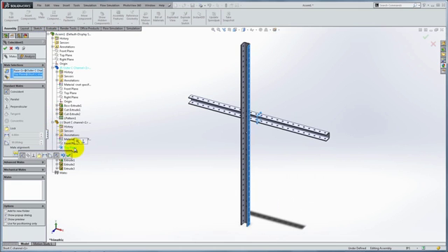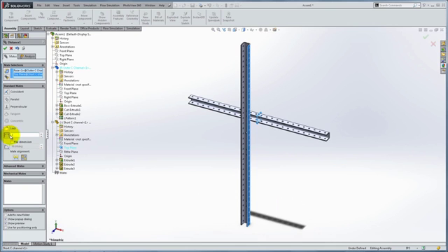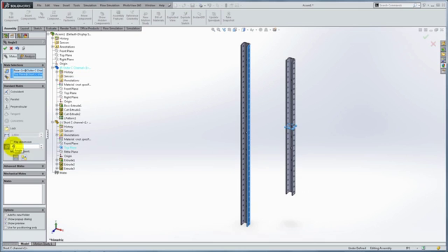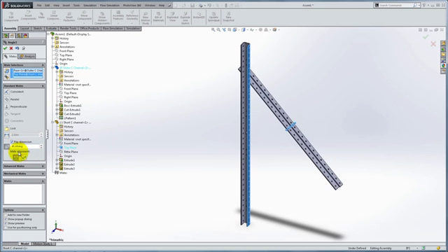Notice how the underdefined part moves so that the two planar faces satisfy the constraint imposed by the mate. Coincident, which means they are in the same plane, parallel or perpendicular, or at a certain distance or angle. You can also flip the measurement direction or the alignment of the mate.